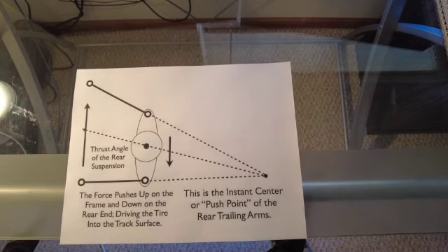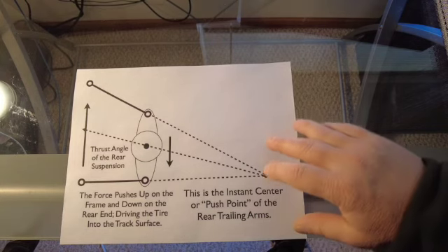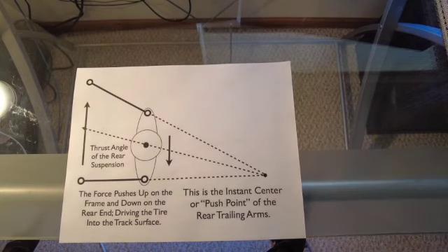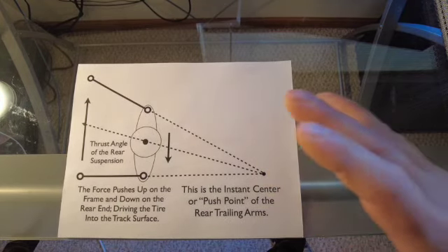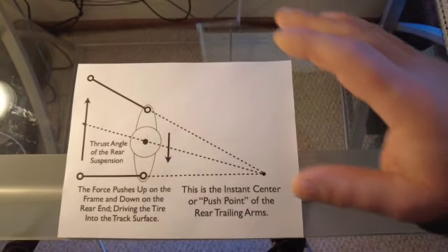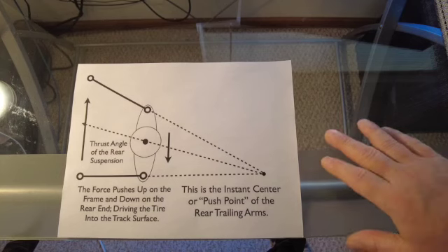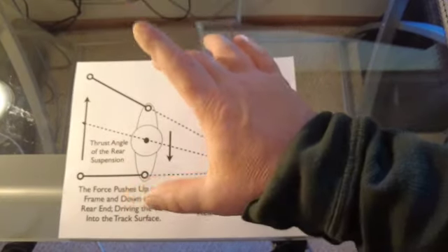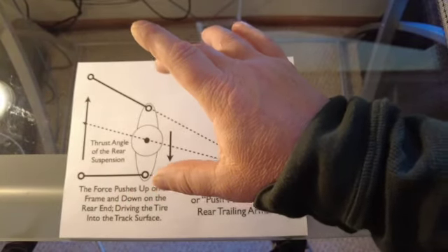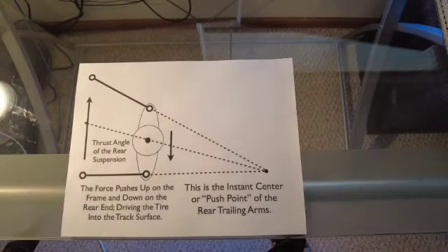Like I say, go and see my other videos on how the push point in the rear and the push point in the front kind of converge and interconnect with each other. This is a kinematic loading point. This will actually push up on your chassis as you're on the gas. So this point here is ultimately important, and to maintain a solid ride height on your right rear is ultimately important. Now, when the track dries out, you may have two settings for the right rear.